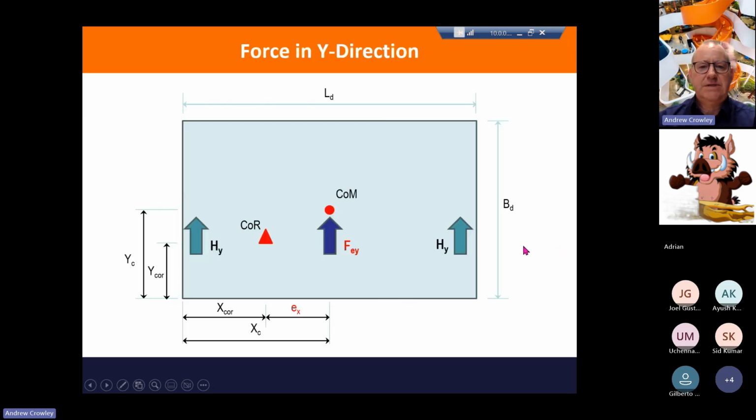The shear forces arising are quite simple. You divide them in proportion to their stiffness. However, because of our eccentricity, we're having a torsion on plan. And this gives rise to moments and gives rise to shears in the walls around the building.